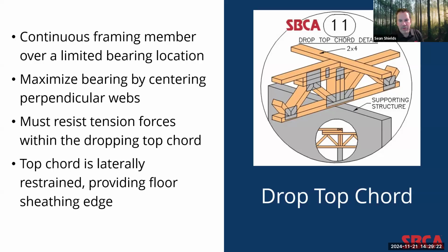Finally, the top chord is laterally restrained at the drop location, which also provides a defined boundary for the floor sheathing edge.